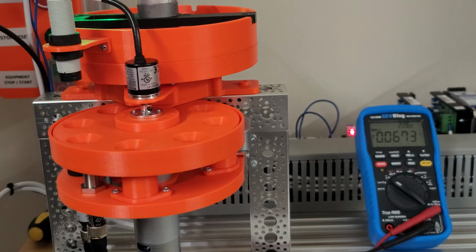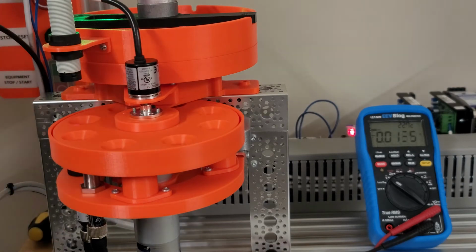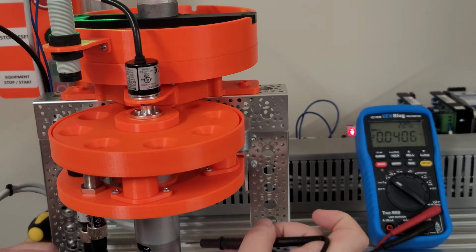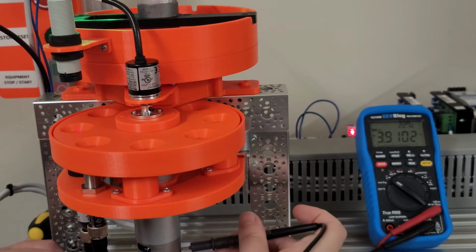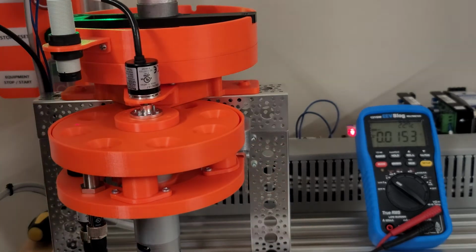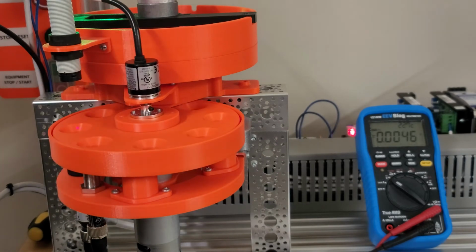That's not exactly what we expect, but let's see if both motors are at the same set point. Down here we have a little connector. This is probably not great, but I don't know if you can see that, the output voltage is showing 3.9 and some change. For one, both of the drives are at slightly different values when they're both receiving the same input, and they're not exactly correct with what we expect.